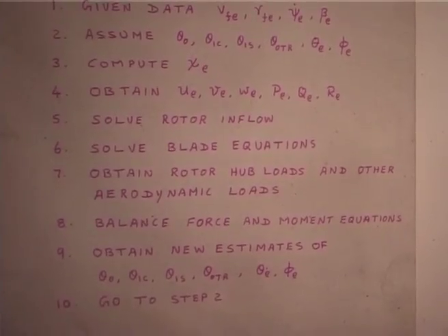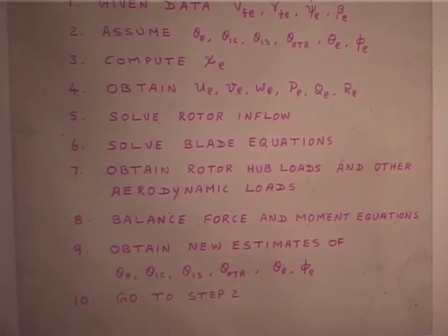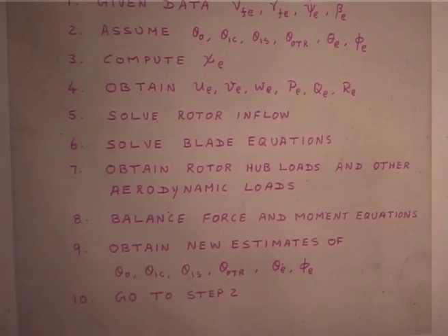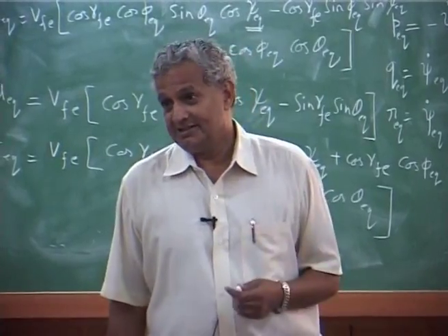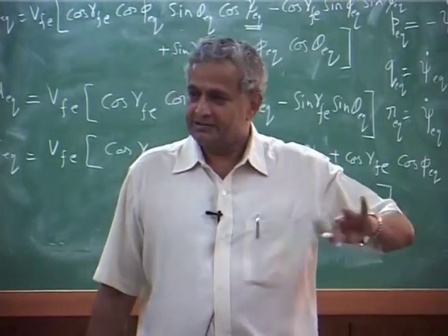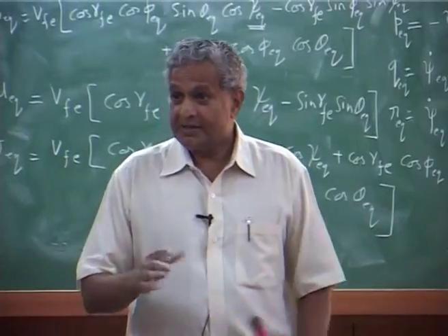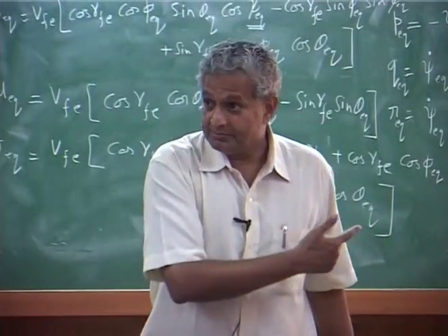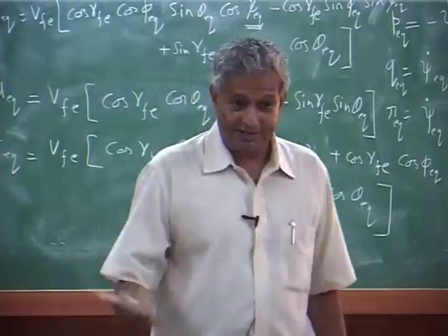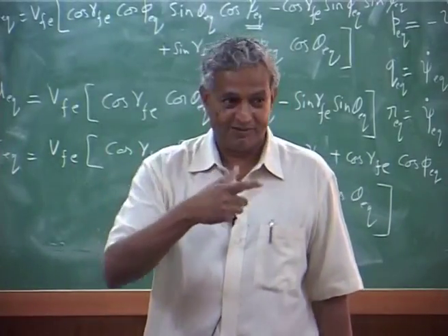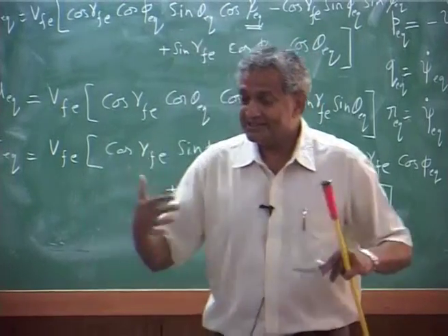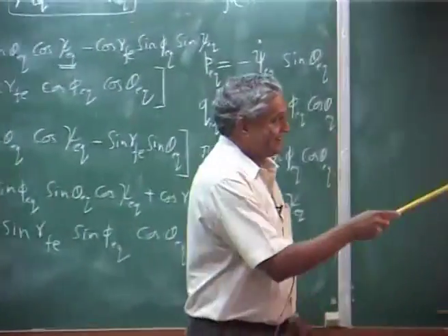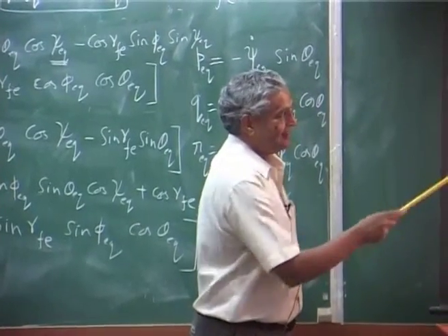So, you can have different types of inflow models. Usually these problems first you try to solve in a simplified way, take only flap, check whether a program is converging, because you will be able to get the mistakes from there. Once it is done, then you can say, okay, these are my loads, and if you want to include stall model, please understand, when I get the aerodynamic load, I should have stall model for the blade. All those things must be, I cannot have a closed form expression, everything has to be integrated in this part.